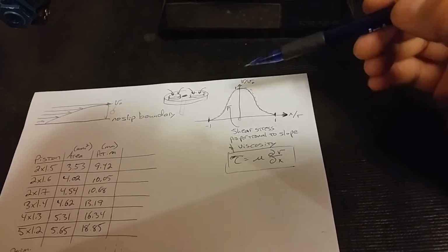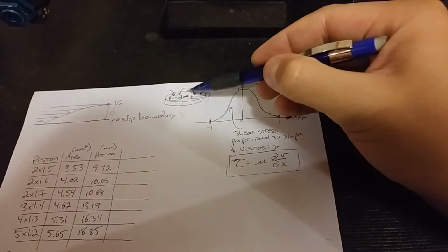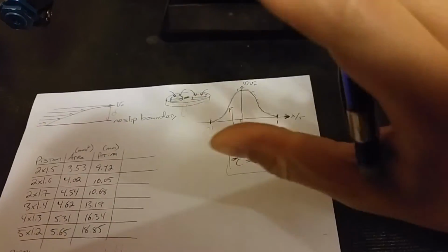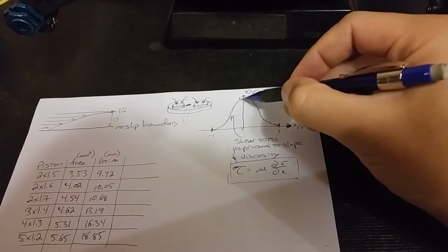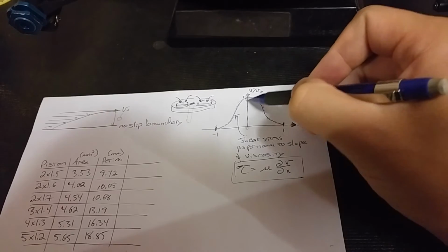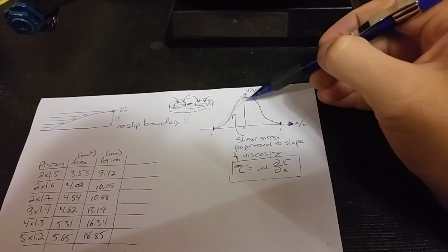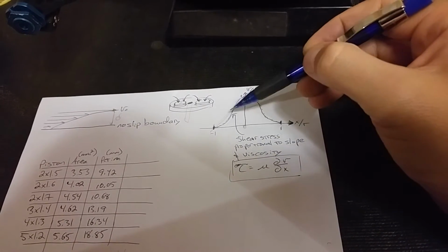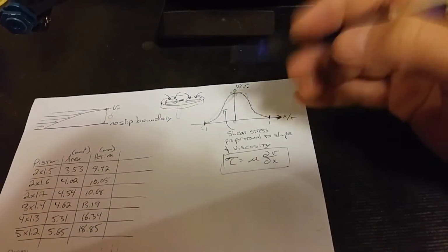What that basically means is as I try to move this piston up and down at a higher rate of speed, the total difference in absolute velocity between the peak velocity here and the edges where it's 0 increases. We could just draw a straight line here. And as this difference in velocity increases, the shear stress within the fluid increases, which means we have a higher resistive force